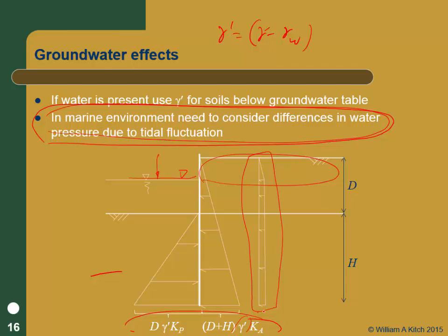No, that's just a gamma. I thought my gamma looked like a 2, so I was trying to make it look more like a gamma. And I didn't connect the little thing to the other side, so it looked like a prime. Gamma prime is saturated gamma of your soil minus gamma water. Boy, that's the most feedback I got in class, how to make mistakes more often. Okay?